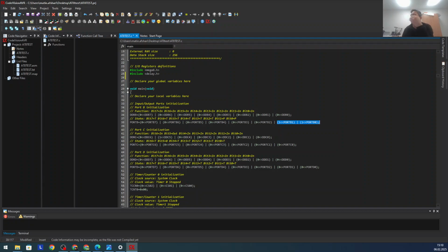That is implemented here. All those selections that we had, it comes here. Then all other pins are 0, you see. All other pins, pins 3, 4, 5, 6 of port B, all of them are 0. It means they are in the tri-state. They are not pulled up like this one.